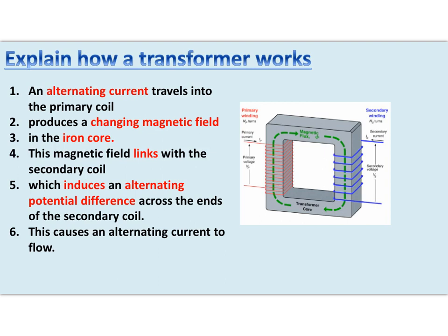So you remember from paper 1 that transformers can either be step-up transformers, in which they would have more turns of coil on the secondary coil here, or they can be step-down transformers, which would have more turns of coil on the primary coil. So you can see we've got more turns of coil on the primary coil, fewer turns on the secondary. This makes this a step-down transformer. So our potential difference is going to decrease: the primary voltage will be greater than the secondary voltage. We get an increase in current because it's a step-down transformer.